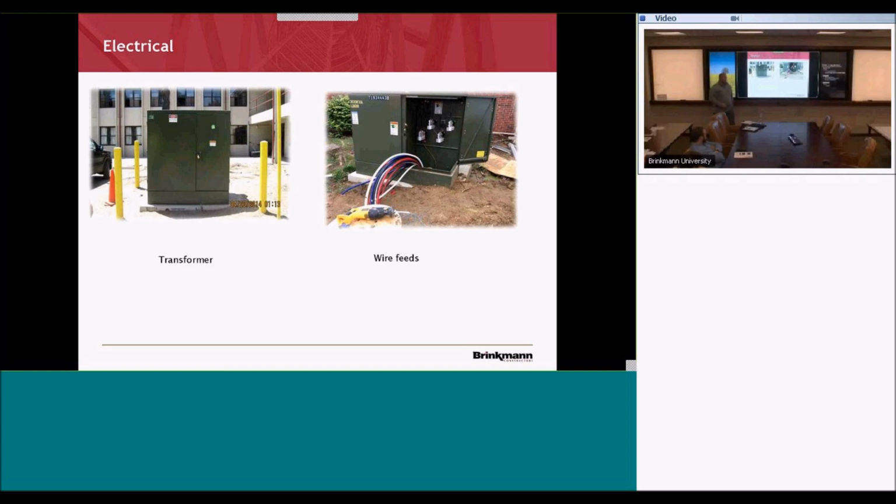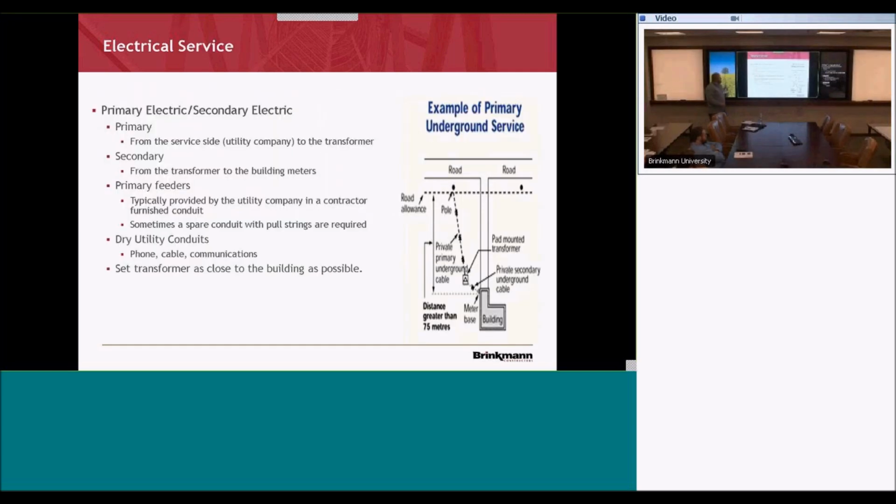What's the value engineering option that we can use when we're pulling that wire? Aluminum versus copper, right? If we can go aluminum, we can save some money. So some things to watch out for though on aluminum is check with your elevator. I know we ran into that at Candlewood. They don't like that. We were able to talk to them up front and get that worked out to where we were still able to use it. But sometimes they require copper feeds to the building. Yeah, if you use aluminum, it typically has to be a larger feeder, which might become too burdensome to pull in particular areas.